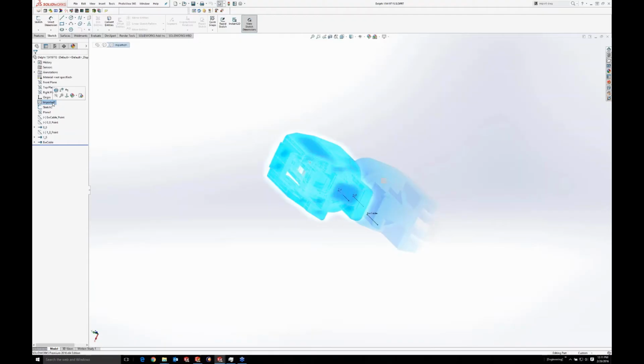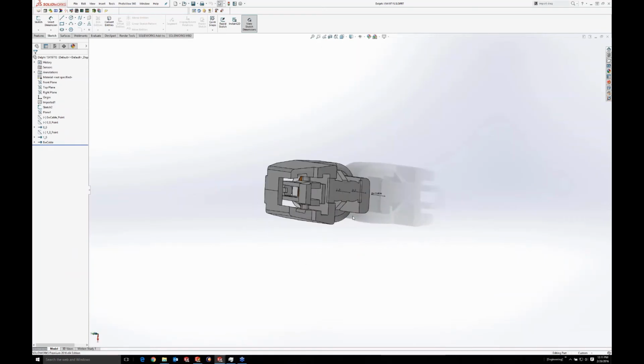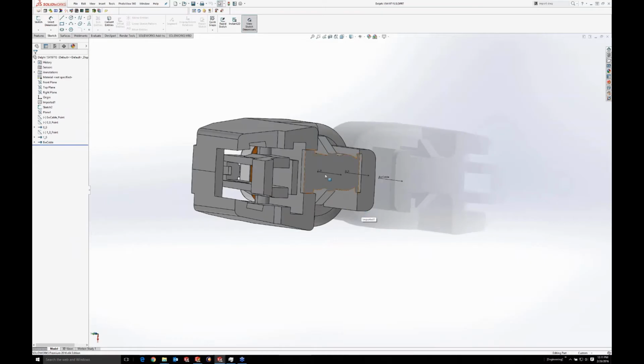You'll see that this is imported geometry. I did not draw this. I imported the IGES file from the manufacturer. If you've used electrical routing before, you'll notice that these look like route points, but they've got some funny names on them. In what's called SOLIDWORKS electrical routing, which I call vanilla routing or plain old routing or dumb routing, we would have things called C.1, C.2 and such. With SOLIDWORKS Electrical, in order for the 2D electrical portion to be able to pick up the data in these 3D parts, it has a special naming convention, and you're not expected to know this.